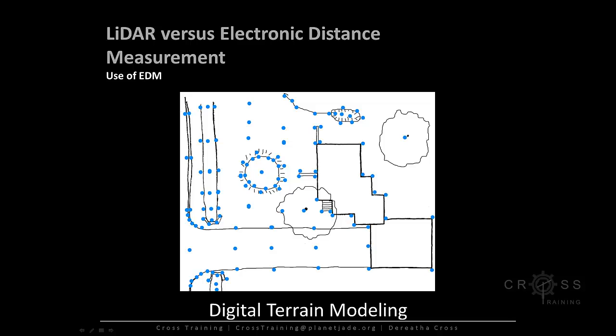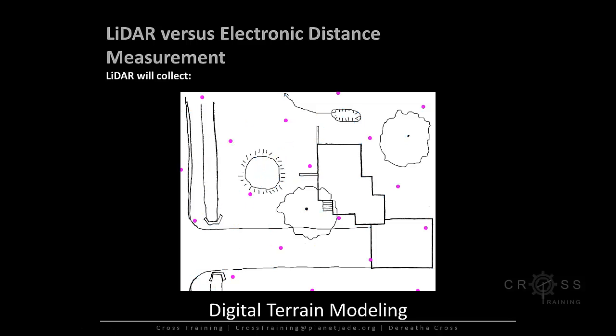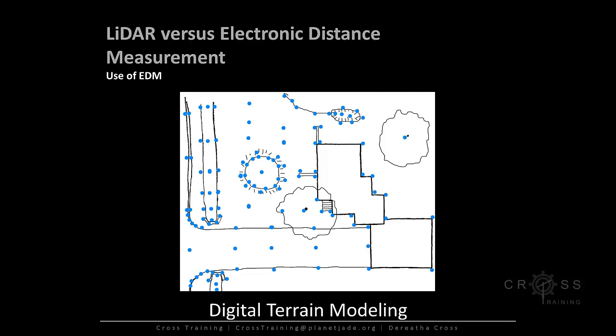But if you recall, with the LiDAR we're not going to get that because that's the best point resolution that we can get. And of course, the technology for LiDAR is getting better and better, so this may not always be the case, but right now this is what the case is. So there may be instances where you'll have to use this electronic distance measurement method to collect data, and this is going to be the most common method for smaller scale sites.